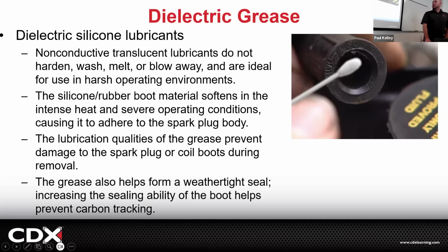But just understand, the dielectric grease does not make the conduction better. It doesn't. It's actually the opposite. We use it as lubricant and a waterproofer. But as long as the system's in good condition, the dielectric grease won't be a problem for that secondary voltage.